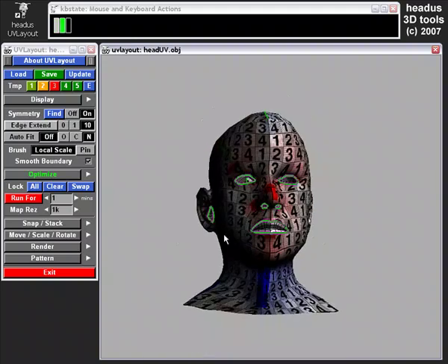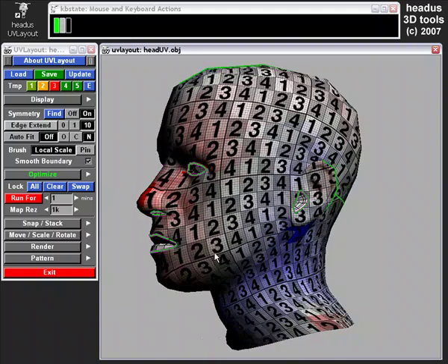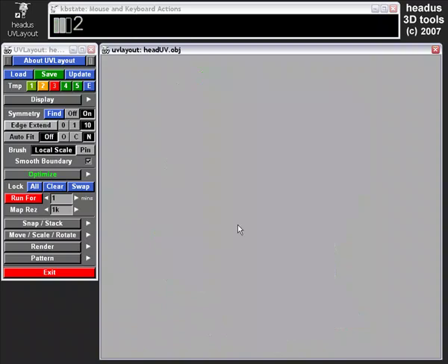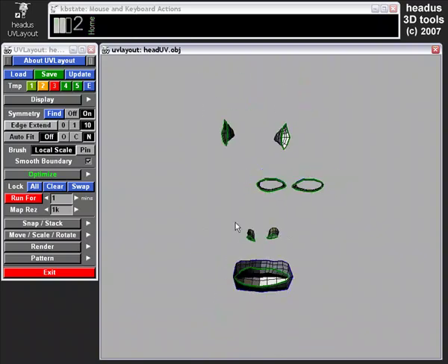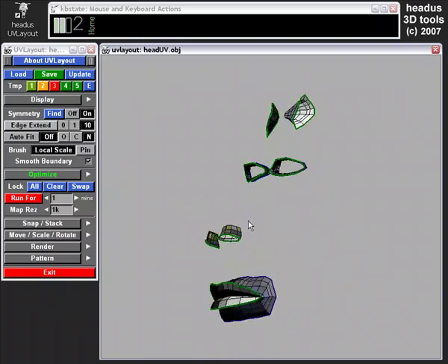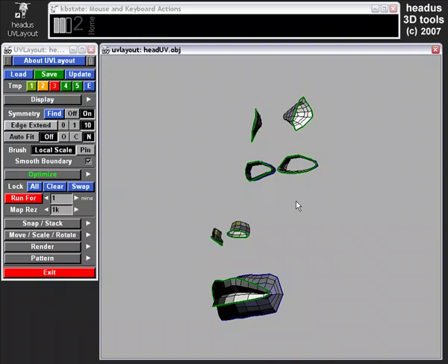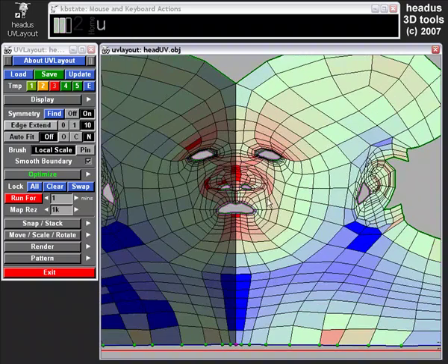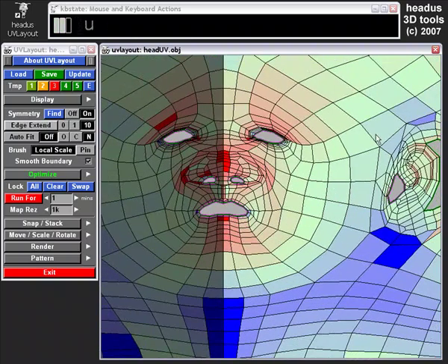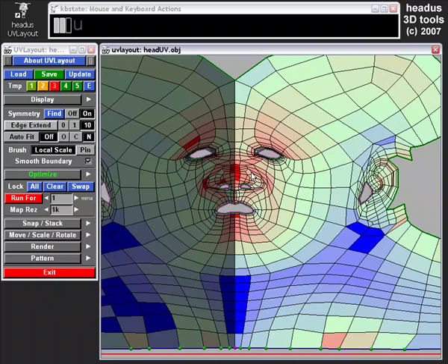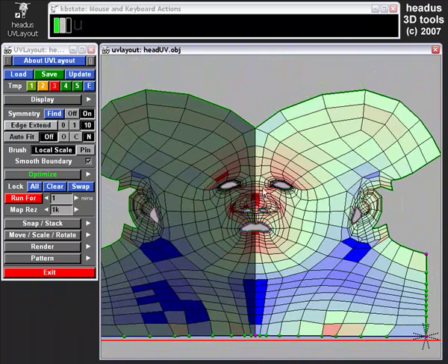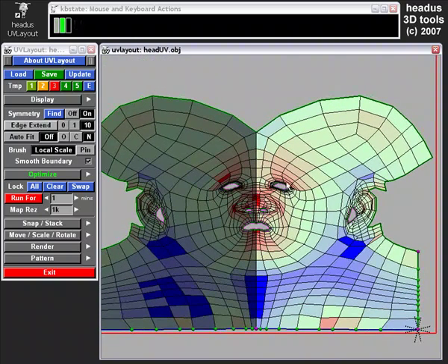The next step would be to take those problem areas that we left in the edit view and deal with these and weld them back into the remainder of this surface, which is looking about right. So that'll be part 2, the handling of the mouth, nostril, eyes and ear holes.